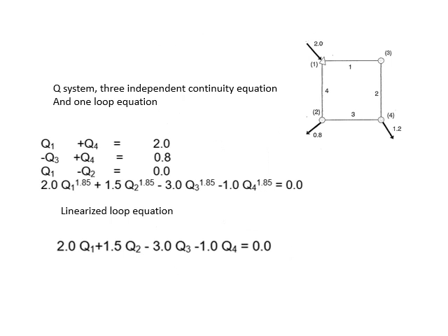The following slides will give 4 different applications of the 4 types of equations for the sample given in the previous slide. This slide shows how we solve the analysis problem for the one loop network using Q as discharge, and we have the energy equation, which is here. The last equation is a nonlinear equation.